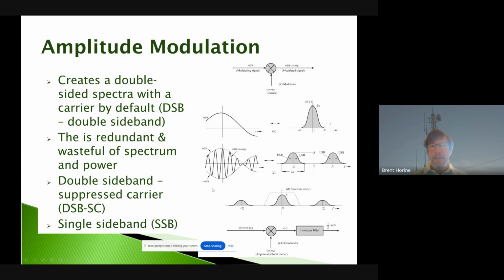So we will sometimes work with single sideband signals, where we construct these things in a more complicated way so that one of the sidebands cancels out. We do some filtering, but now we're only having to send one of the sidebands, the single sideband, and we can put all our energy into that instead of having our energy divided between these two redundant signals.